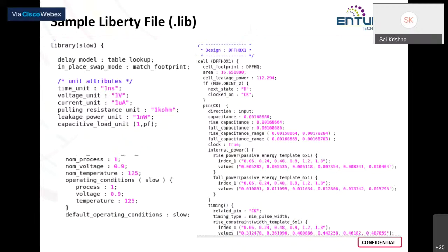Now, one important point to be noted here is that this directly proportionate relation between your temperature and the ease of charge movement is applicable only till 65 nanometer technology node. For the technology nodes below 65, both higher and lower temperatures will slow down the charge.